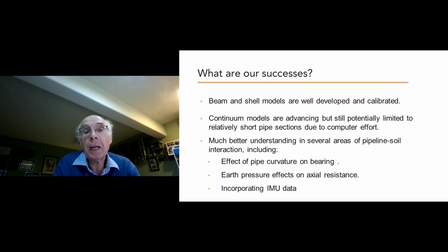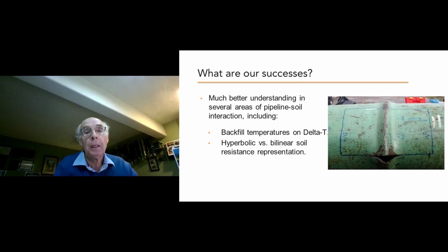We have much better understanding in several areas of soil pipe interaction, including the effect of pipe curvature on the bearing capacity or the downward bearing spring. We have a much better understanding today on earth pressures and their effect on the axial resistance in drained loading. And we are much, much better at incorporating smart PIG inline inspection tools and IMU data into our soil pipe interaction. In addition,